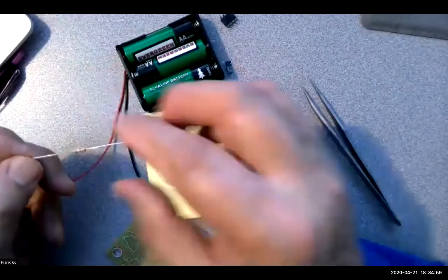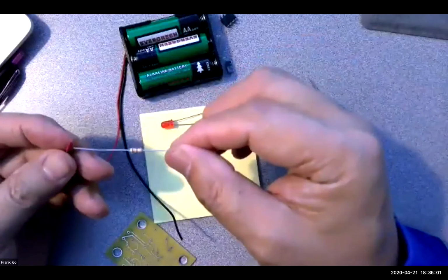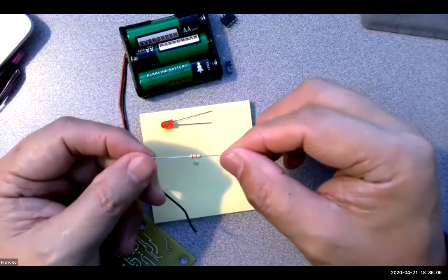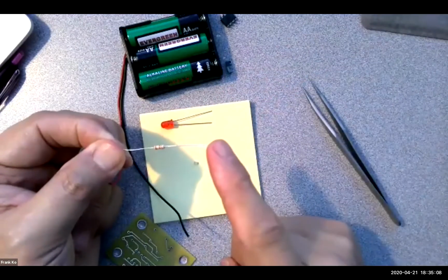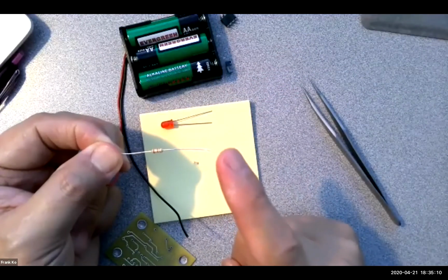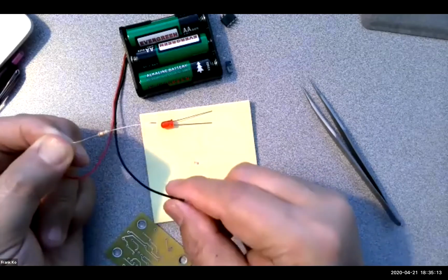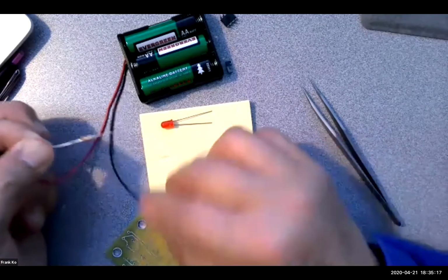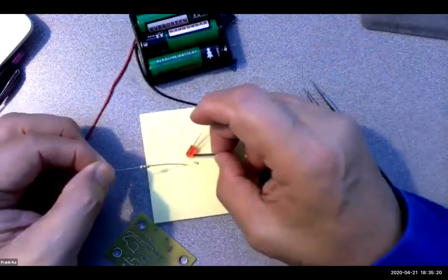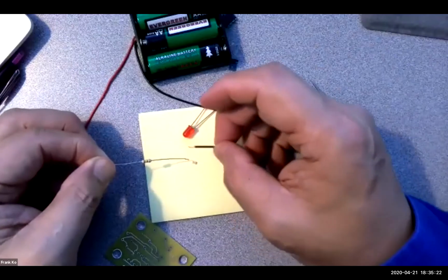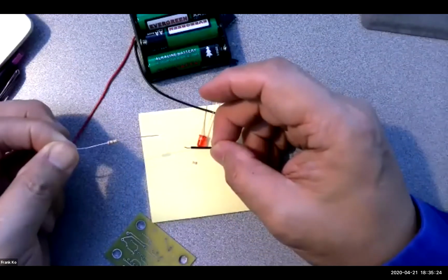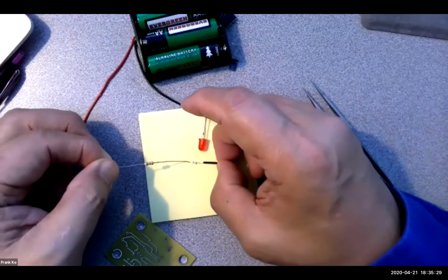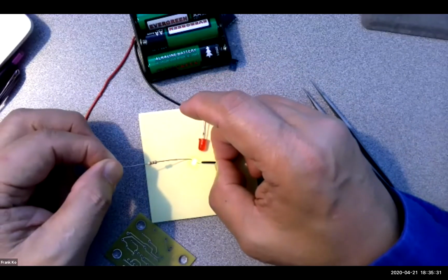Now, to test the LED, I'm going to take my resistor and connect it to the positive lead right there. So this is the positive end. I have to have a current limiting resistor to do this test. If I don't use the current limiting resistor, if I connect my leads directly to the LED, you will have burnt it out. So watch carefully. We're going to check the polarity. I have the negative lead in this hand and the positive lead in the other hand with the resistor. And if I touch it a certain way, you see it light up?